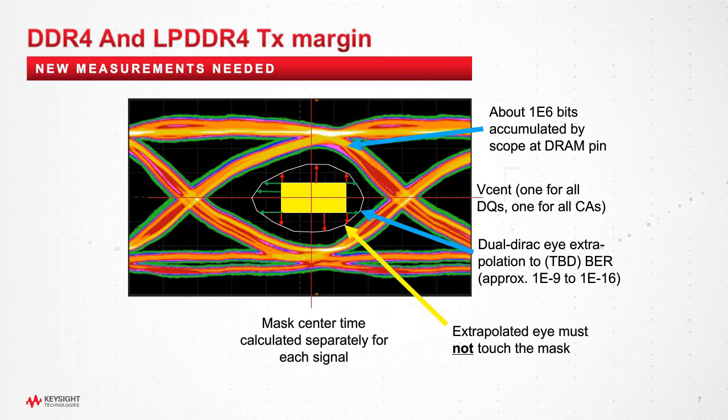So when doing designs with DDR4 and then trying to characterize how reliable your system's going to be, a lot of folks really focus on margin. And of course, you want to have a design that's got margin in it. In the past, margin would be defined by how much actual setup time you're providing beyond what the spec requires and how much hold time you're providing. Whether your voltages are exceeding the VIH, VIL, AC, and DC especially.